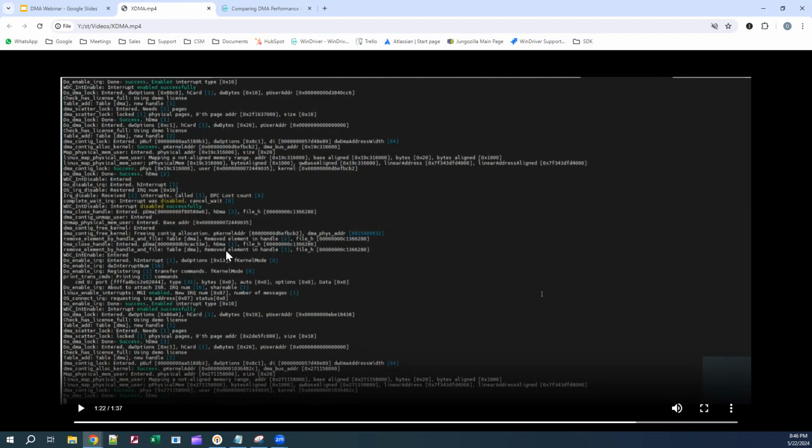Another thing I added to this video, and I think it is interesting, is the debugger. Okay, at the beginning of the video, we opened the WD debug utility, and here we can see all the prints of the debugger. What is it good for? It monitors your program, and you can see what's going on on the backstage. If things are not working properly, you can see what happens.